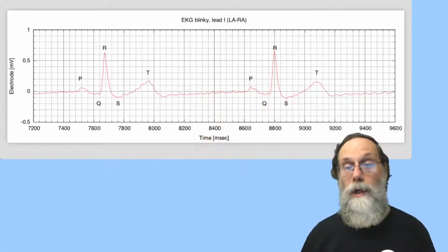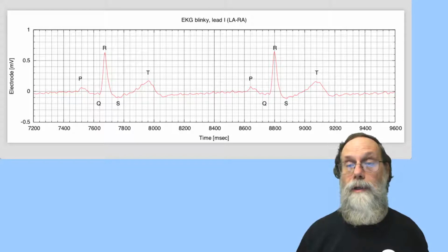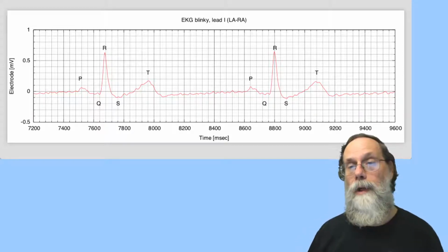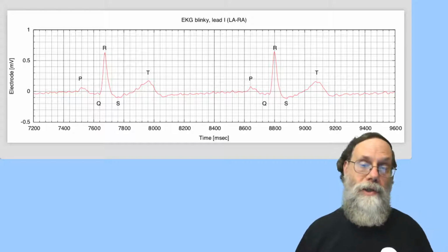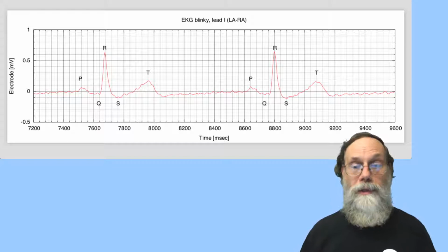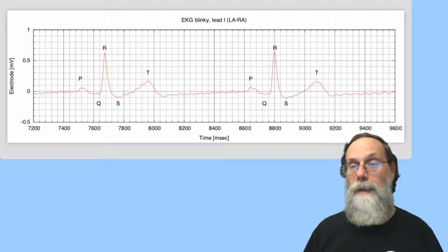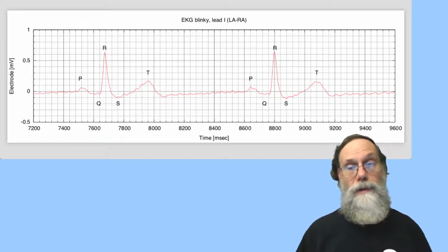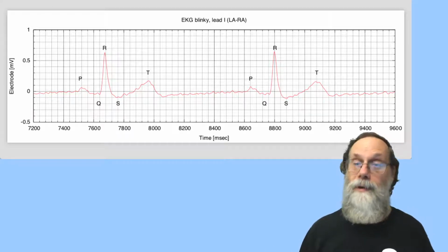Well, to start with, your goal is to produce a plot, somewhat like this one, using signals from your own heart. So, what does a full design mean? It means you've got to start with the specifications. You've got to come up with your own specs. What sort of signal are you going to have coming in? What sort of signal do you have to have going out to your data acquisition system? What discrepancies are there between these things?